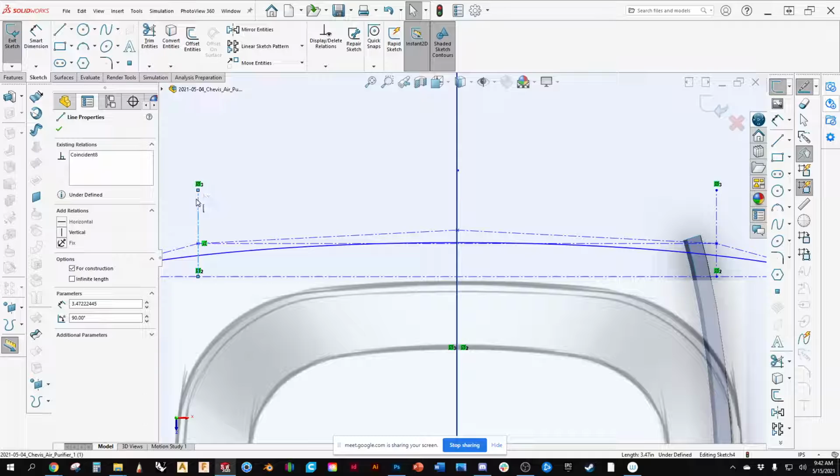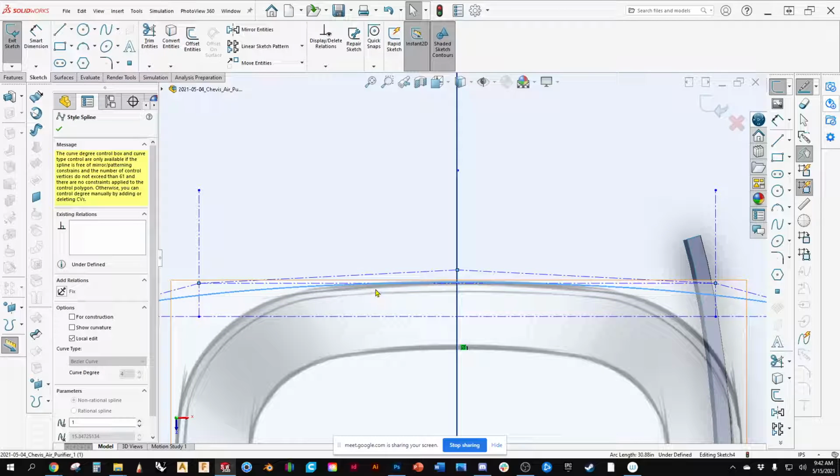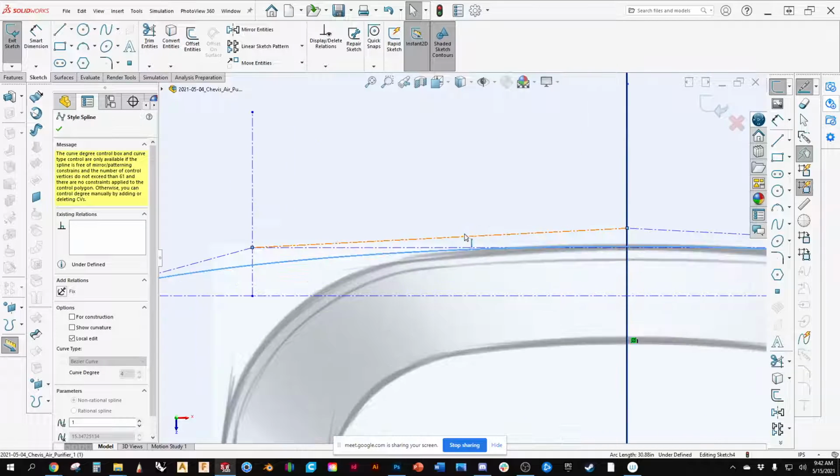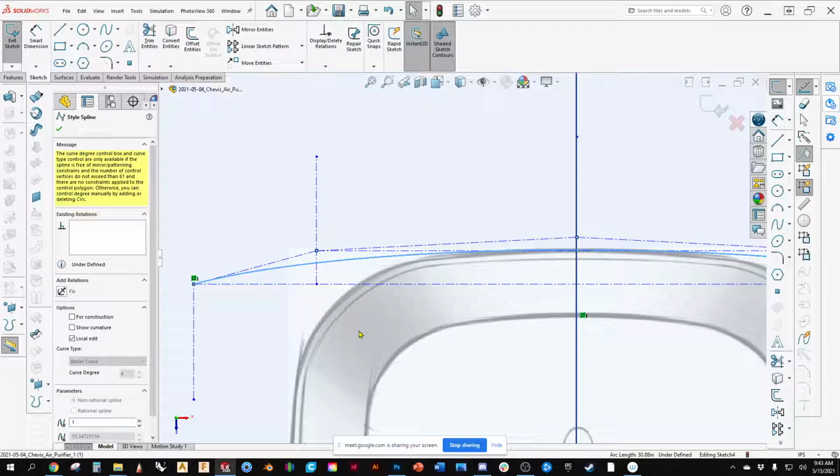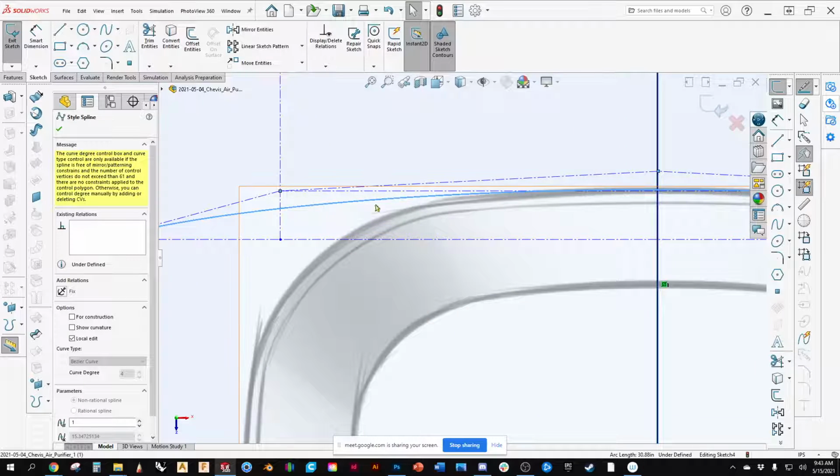Now, where I laid out the construction lines first and snapped to those points, if for some reason you miss something, you can do it afterwards. So we're going to come in and say, that's what we want. The reason I'm going to do this is because I look at this round as a transition surface. A lot of times, your length and your width are going to get adjusted. But for us as designers, if the radiuses are extremely important, which for this model they are, because you want that clean, soft look, I want to have greater freedom over this.